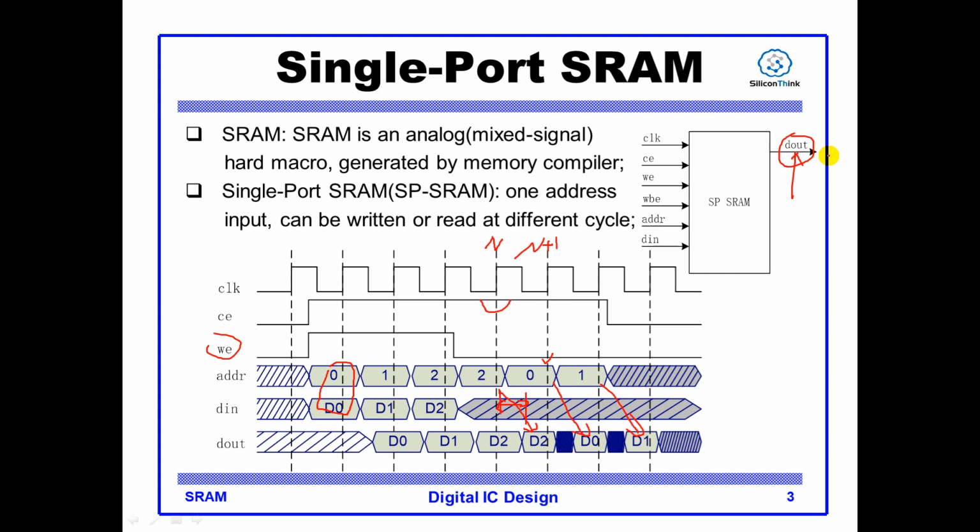If you want to do a high-speed design, such as making the clock frequency much higher, try to put as little combination logic as you can at the D out point.